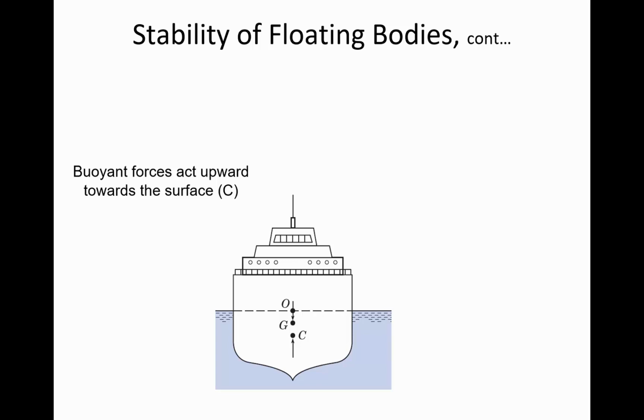And some cargo ships, if you've seen video or maybe even in person, if you've seen a container ship, sometimes they'll have layer after layer after layer. They may have 10 or 15 stories of those metal shipping containers on the deck of the boat. And so that can bring the center of mass very high. That's kind of the case here. We have this cargo boat, and the center of gravity, G, is relatively high because there's so much mass above the waterline. Now they still are going to put some ballast below the waterline, but the location G isn't dependent just on the shape beneath the waterline, but on where the mass is in the boat.